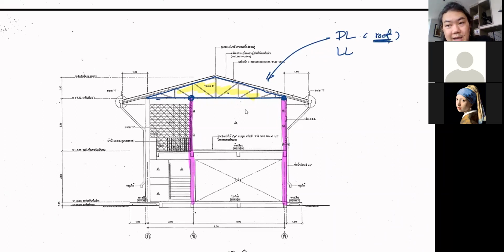When you have selected the roof, first, you will know how much it weighs. Second, you will know the requirement of the purlins, because when you have the roof, you must arrange your purlins to support the tiles. And each tile will have its own requirement for the spacing of the purlin you need to have.